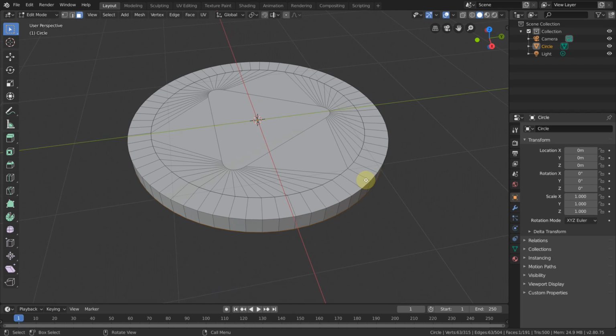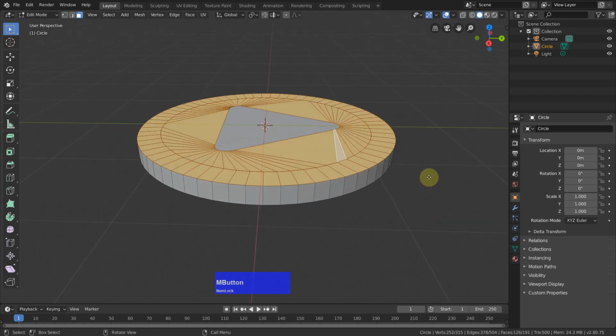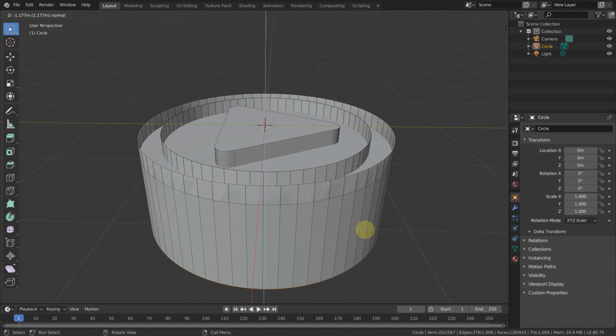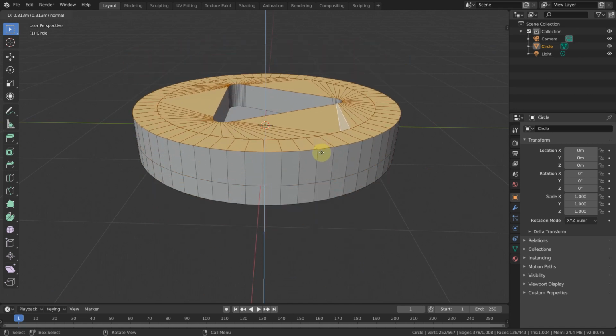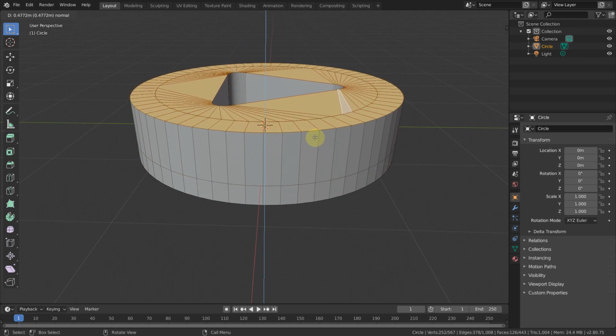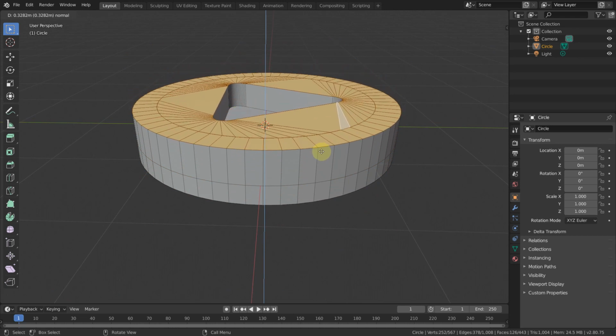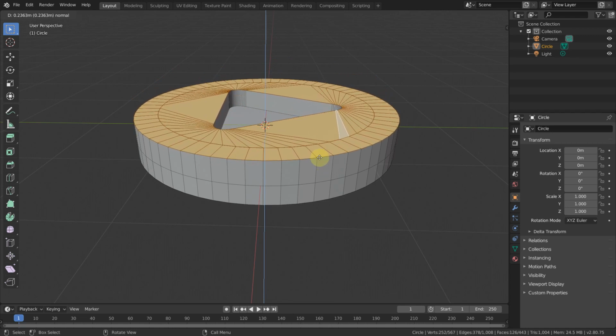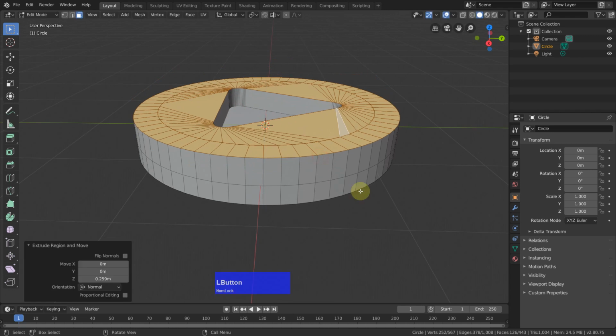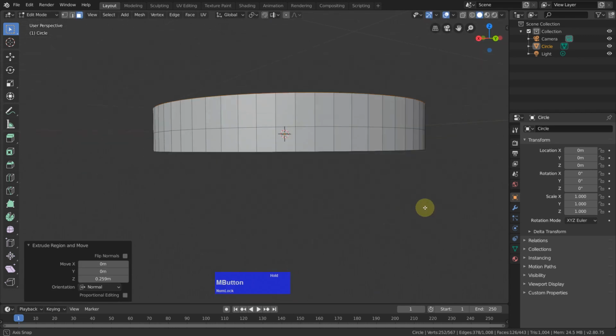Now I go to polygon mode or face mode and Alt left click select these and Shift, Alt, left click, select these, then E to extrude, and if we get this blue axis, it means we don't have to give the direction. Blender knows what direction we want to extrude, and so I extrude this up to here, about.